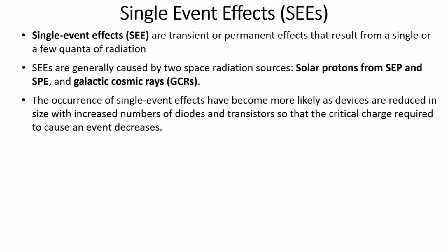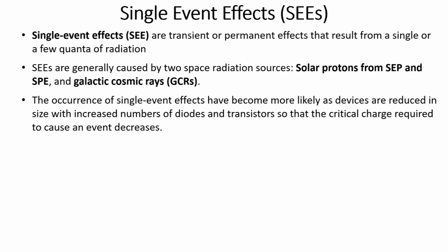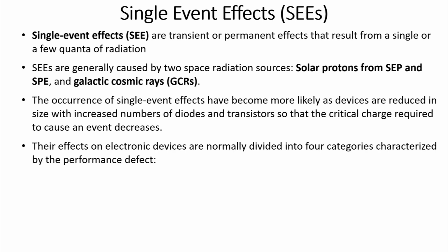Because of that, the critical charge, or the energy of the charge, which is required of the incoming particles has decreased, because of the technology advancement in integrated circuits, where miniaturization is happening day by day. So, this has made single event effects more and more prominent with the advancement in IC technologies. We will see that one by one.